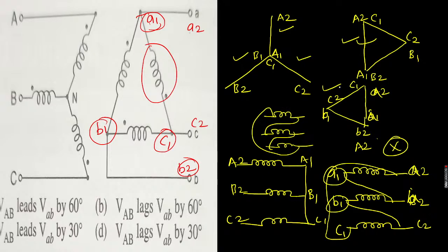So anyway, coming back to the conclusion, in our question they have given only this diagram, and one more thing, some data is missing, right? I am going up with my own data. In the last case, we drew for the positive sequence. When we are drawing it for negative sequence, this case will be opposite. For positive sequence we went this way. For positive sequence, where did we start from? We should start from A and then C and then B. Same sequence. I have to start from A and then I have to reach C and then I have to reach B.